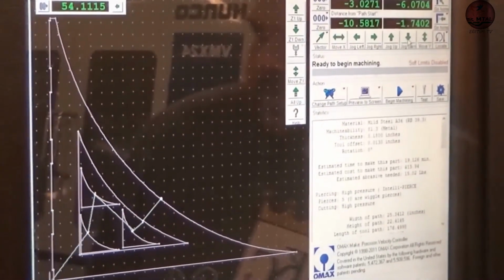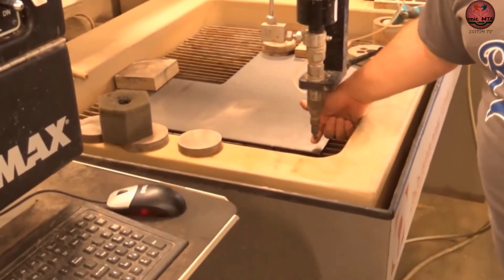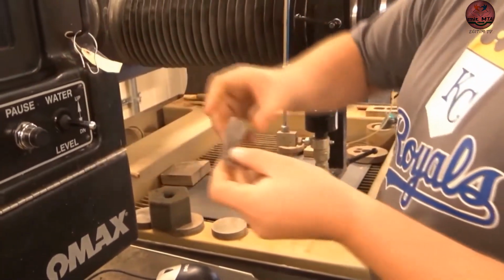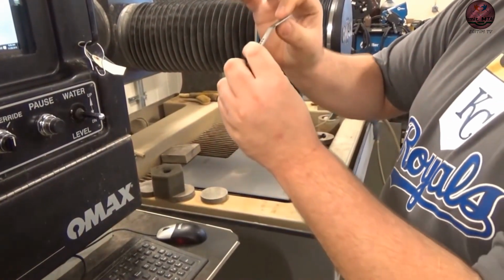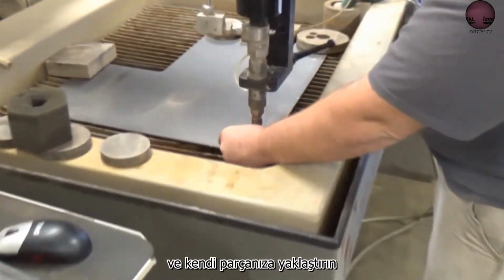But I still need to set the height of my cutting head right here. So this has to be a certain height from my material. And we use this tool. This is a tool that always hangs right here. It's from Omax, and it gives you about 60 thousandths distance if you screw it down and get it close to your part.